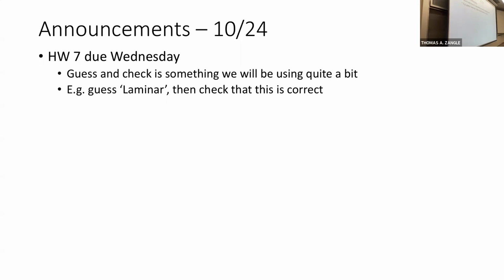So in the energy balance, remember we had the velocity terms, kinetic energy terms on either side dropping out, because V1 is equal to V2, right? But the velocity shows up in the friction factor, in the head loss due to friction, in the energy balance, right? You need to know velocity to know the head loss due to friction. And so you need to make some assumption about velocity and figure out the friction factor in order to get that head loss due to friction. So you do need velocity. And in this case, all you know is laminar, so it's reasonable to start with laminar. Okay, yeah.